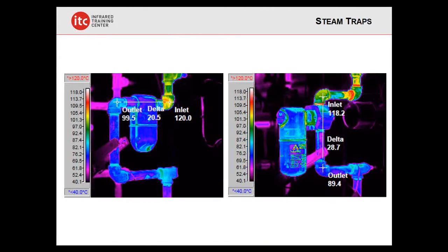With steam traps, obviously with ultrasound we can listen to steam traps, but with infrared we can find temperature differences. And that's what we want to look for, a temperature difference from the inlet to the outlet side. With this type of thermography, by the way, I don't want to steal a term from another area of the industry, but it is kind of active thermography in the sense that you want to be actively looking at this as it is happening, right? As the trap is cycling. It's not just taking a still photo and walking away. You want to see this cycling, right, Gary?